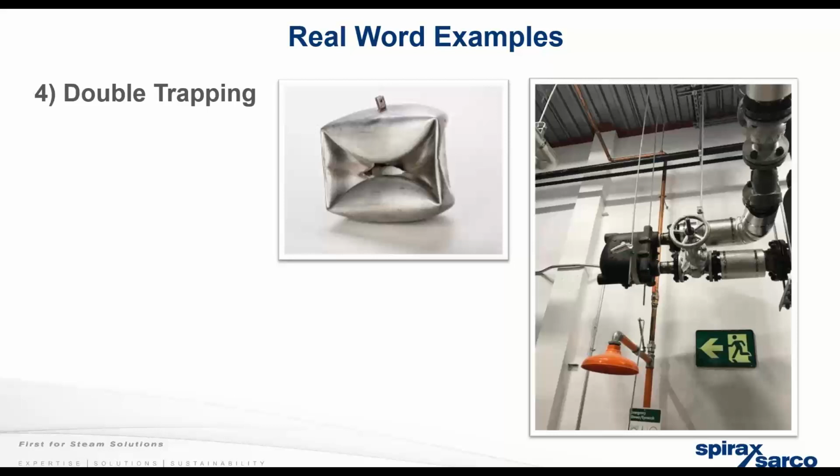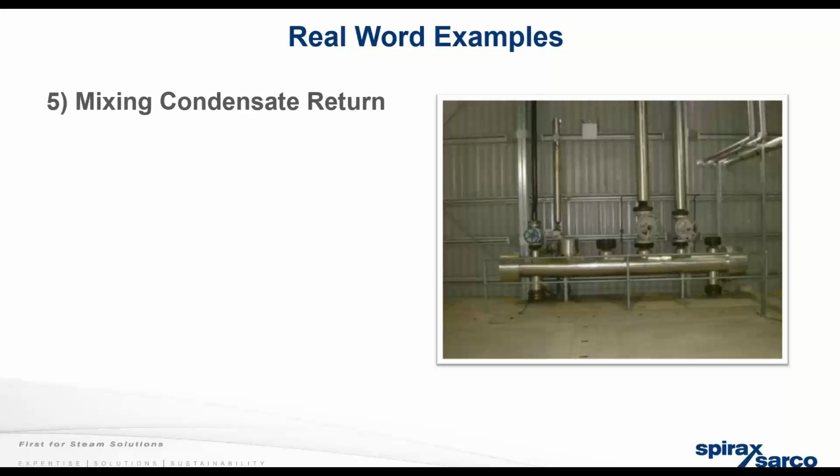And the water hammer was obviously quite substantial. Okay, this is very, very common. Seen this at multiple hospital sites recently. Looks great, 100%. Looks like a steam header. Except these are condensate return headers that were piped in perfectly by the contractor, by the engineer.